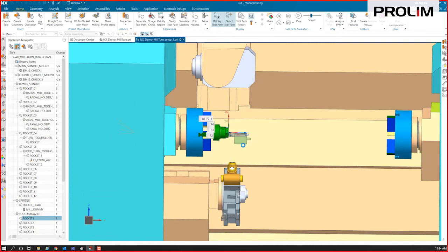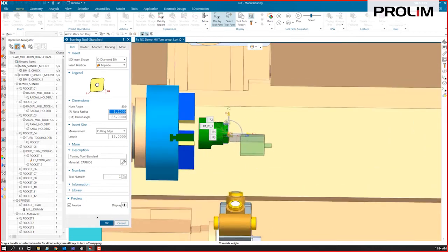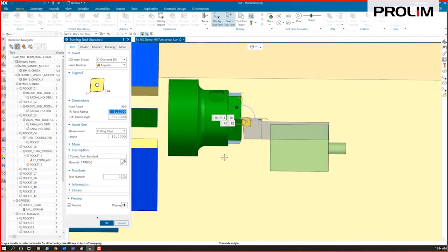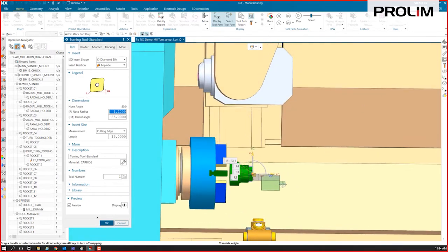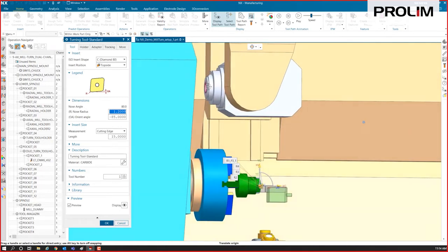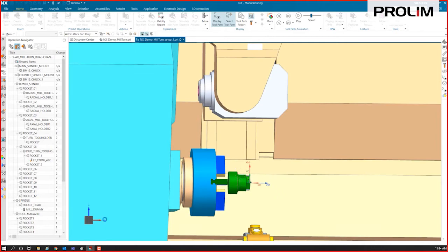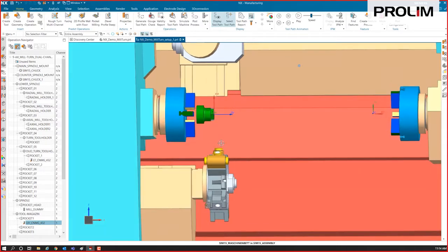Now this one's slightly different. I want to make sure that I have this one oriented the way that the upper head retrieves it from the tool magazine, which this is oriented correctly then. Everything's set up correctly on this one. So I'll keep the adapter as well, just as how it's going to insert into this upper head here. So I can just select OK to that one. Now that tool is going to be in here as well. So we've got those two tools set up.